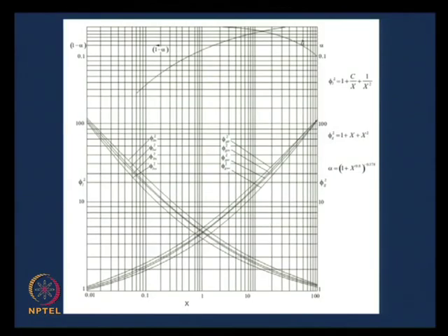But very frequently what people do, they find out the frictional pressure gradient from here and accordingly they calculate the gravitational and acceleration components and they can calculate the total pressure gradient. That is also done for this particular case, and we find that the correlation which I have shown you graphically here, in essence it balances the frictional shear stress versus the pressure drop. This particular graph. Okay.